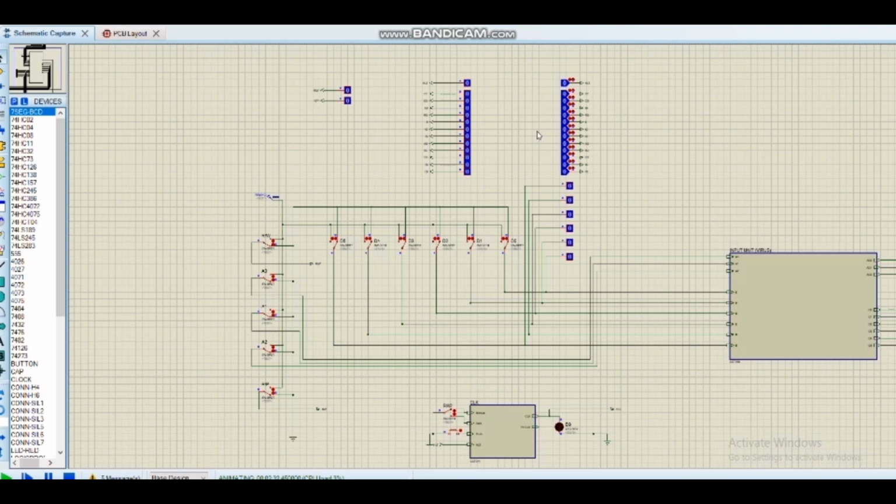So we first give our RAM location 000, and we will be storing 000 and 110. The first 000 indicates our opcode for load, and the second 110 says to load the data which is stored in RAM position 7. And then again we change our address location to 001, and we give input 001 and 111. The first 001 indicates the opcode for our add operation, and the last 111 indicates the 8th position in our RAM.